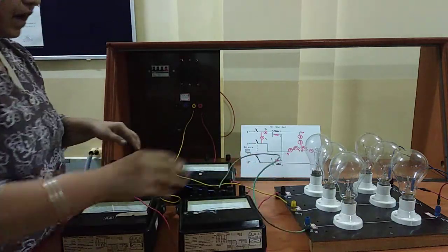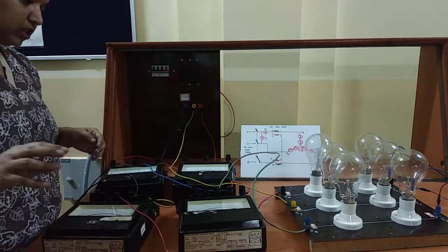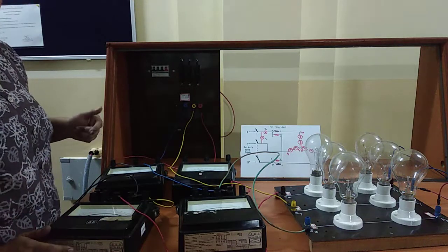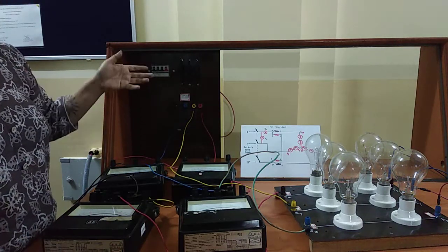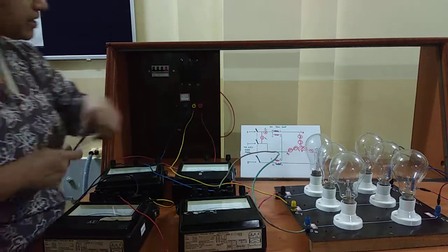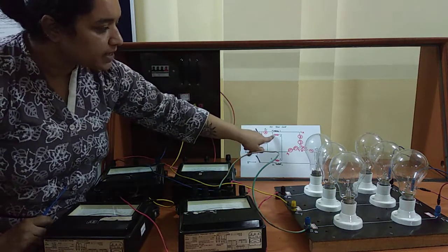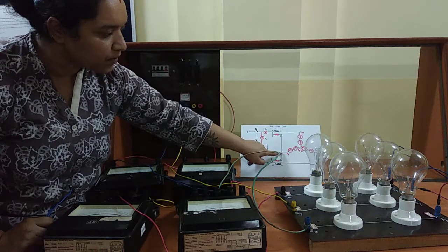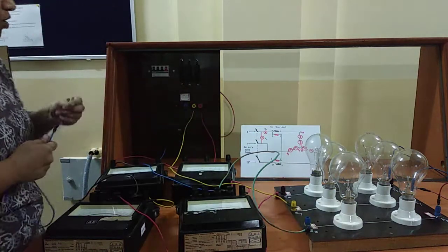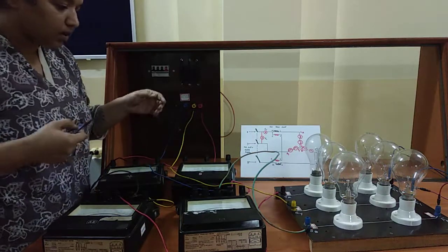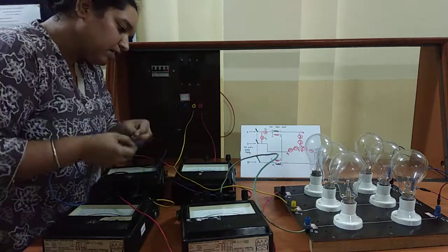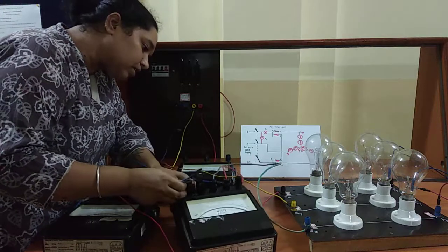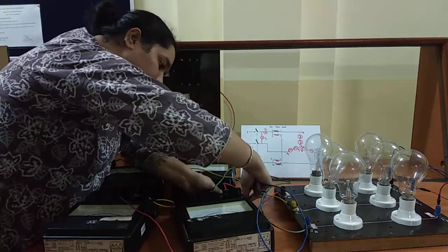Okay, now we should connect the potential terminals of both the wattmeters, isn't it? M and C is shorted. C is internally connected with V. From V, we have to bring it to the point where it is connected to SY. So, in C, we are using the voltmeter range of 500 volts, isn't it?